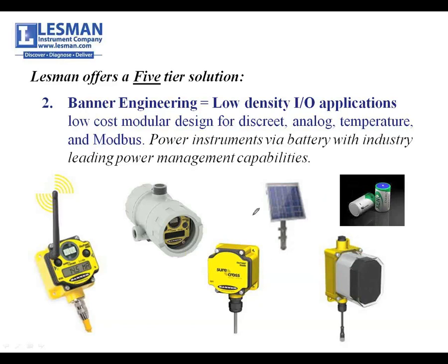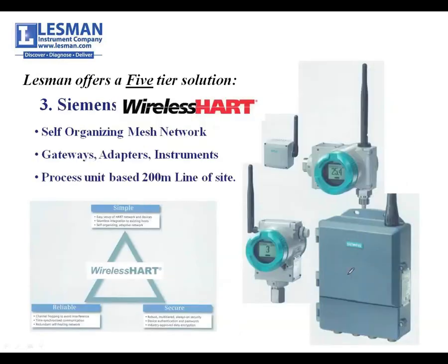Now, I also threw in a solar panel in here. They're very good at solar. A combination of a solar panel and a 6 battery pack like this guy over to the right. There's 6 D-cell deep cycle lithium batteries in there. That combination is not a bad value and is a great way to measure depth of pits, lagoons, things like that. Banner's very good at low-density I/O applications where you have 2 or 3 things that you want to gather in and send. The Banner equipment is very easy to add radios to the network. They do a real nice job. It's a nice fit for us.